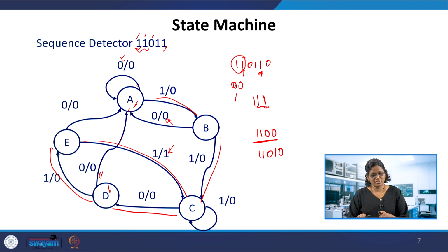If we get the digital circuit equivalent of it, you can instantiate the D flip-flops and then a few combinational logic gates for the next state logic and the output logic. The Verilog module can be developed in that fashion also. That is a separate model, but we consider this as a state machine, so the way of developing the Verilog module could be the state memory, next state logic and output logic blocks with always blocks.